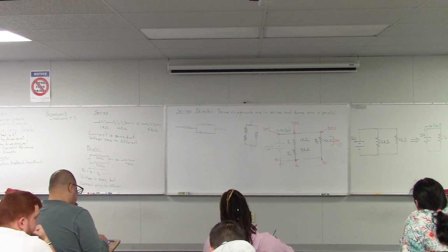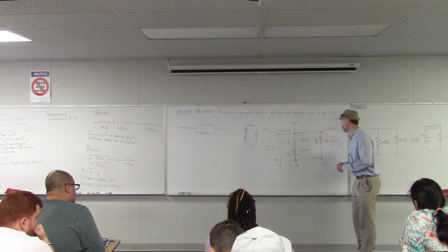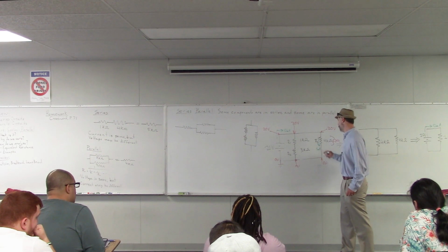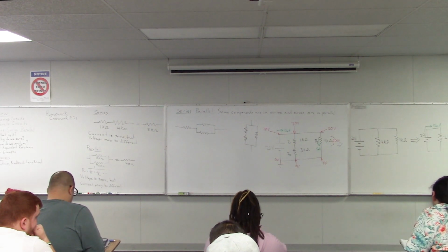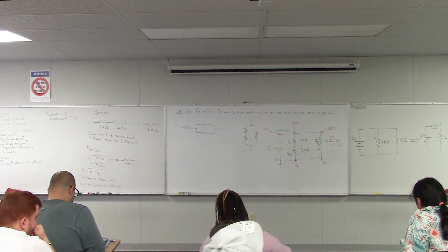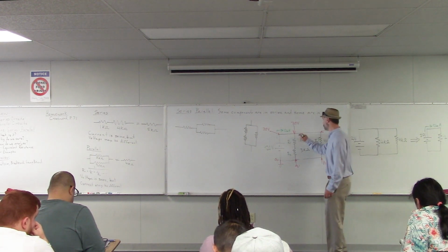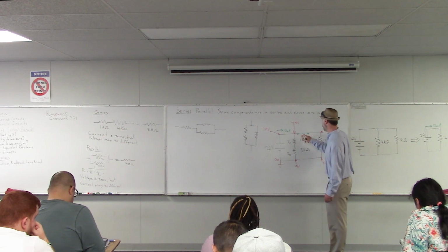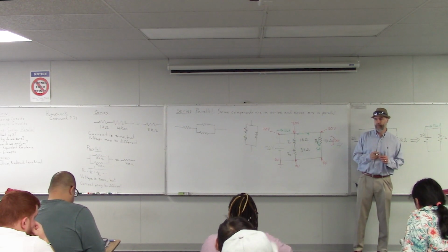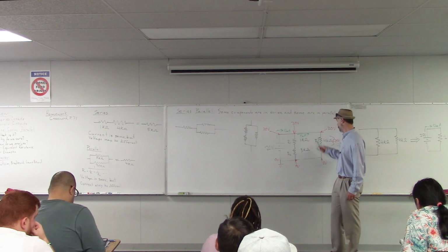So that's the current that's flowing through R3. And I can write that down for my current here for R3. Perfect. So how much current is flowing through this wire in the circuit? Yeah, 5 milliamps, exactly. Because that all flows down through R3.